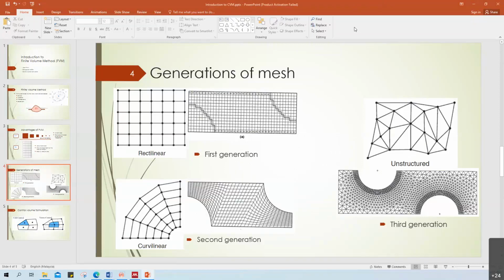So what you mentioned was again spot on. It depends on the software, as each software requires or accepts a certain type of mesh generation. For example, once you move away from commercial software like ANSYS, which is quite convenient because it has in-house mesh generation, open source software mostly doesn't have meshing capability.